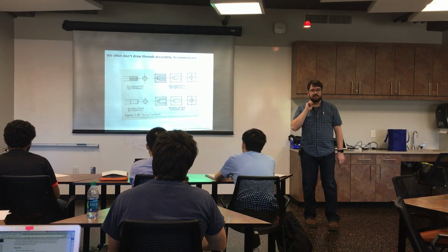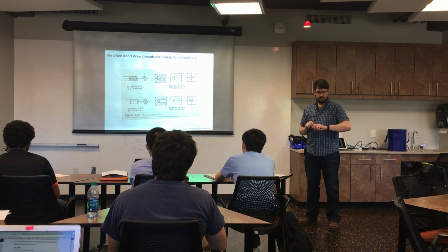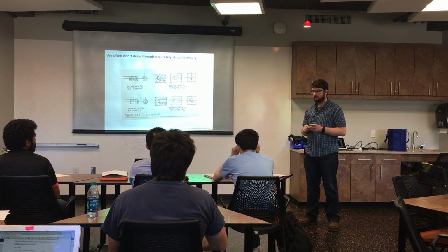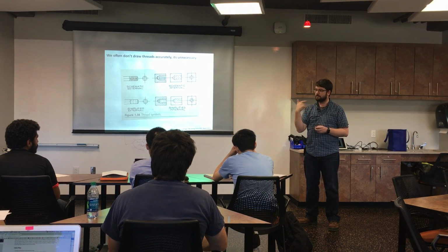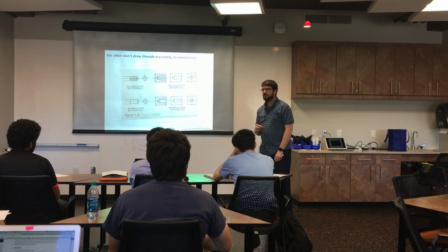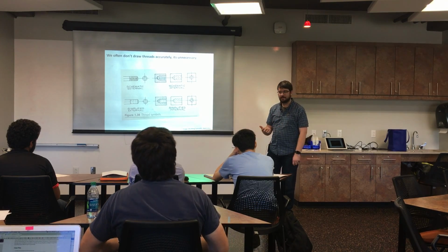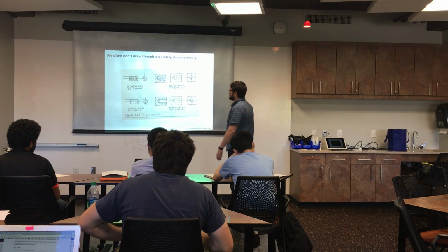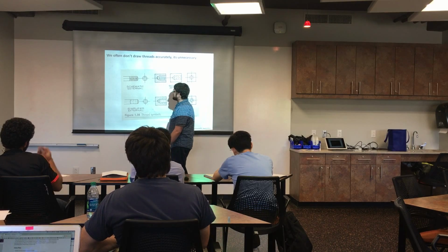Things like threads, even in 3D modeling programs, we can model them where it actually has the proper thread pitch and 60 degrees, all that, but we generally don't. We're going to use a tool like a tap that you all have used now and run through there to create the threads, so we schematically show them.